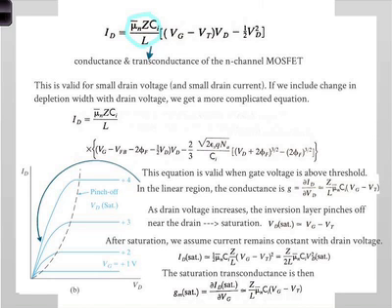But of course, the other things are the mobility, which we talked about. Mobility turns out to be important, right? Remember we talked about our quantum well devices with high mobility, and the same principle is applied here. Also, the gate capacitance, right? So you want high gate capacitance, which means that you want that oxide thickness to be very thin. Remember, it's inversely proportional to the gate capacitance. I told you before that all the advanced devices have very thin oxide. That's one of the reasons.